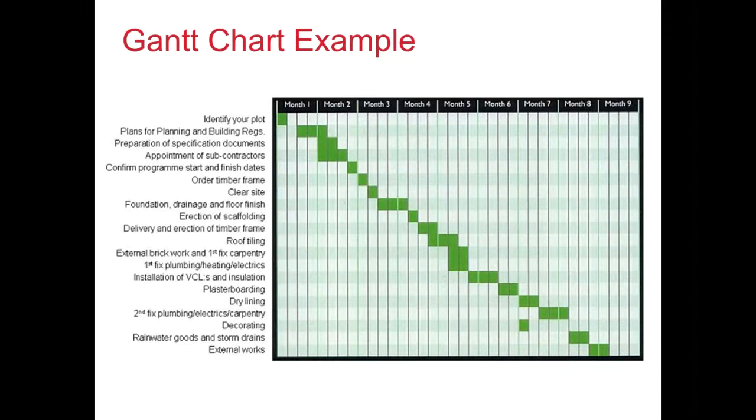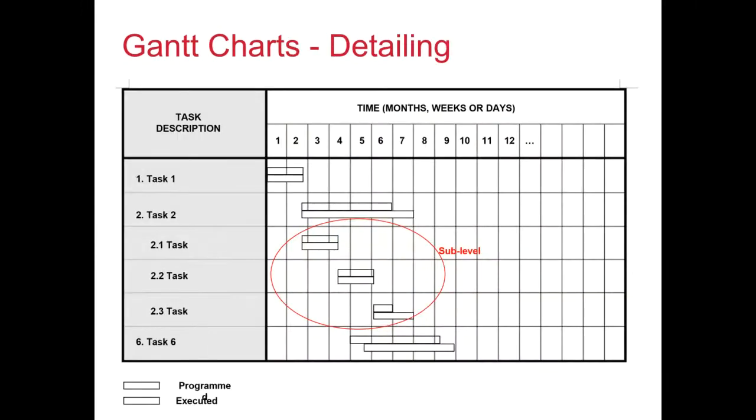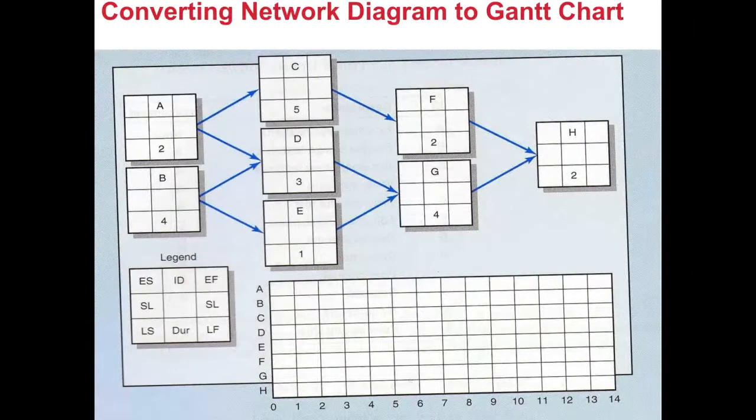So here are some other examples from a construction project. And then we can see this work breakdown structure and the visual representation of this work breakdown structure on the right hand side. So we will see how we create this bar chart. First of all, we start with the CPM calculations, so 0, 2, 0, 4, and then this 2 will now either we could use 2, putting in activity D, or 4, and as it's a merge activity, we will be choosing the largest.